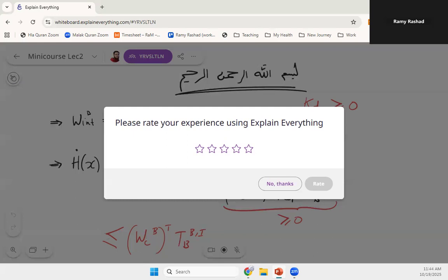The same idea. You can use a robot arm as the environment, and then you have your own robot with the controller, and it would show that a passive controller dealing with this passive environment is stable, and a non-passive controller dealing with the same environment is unstable. Of course, this environment itself has to be handcrafted, very complicated and very nonlinear, in such a way that we really show it is possible. A wall doesn't have a lot of dynamics, it's not moving. But if you have tree branches, this is already a dynamic environment with dynamics of its own, for example if you're doing crop harvesting with a robot.